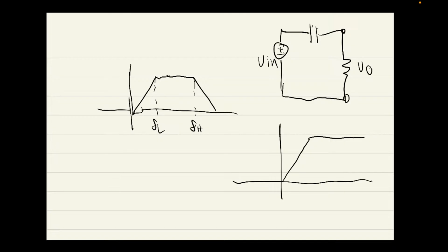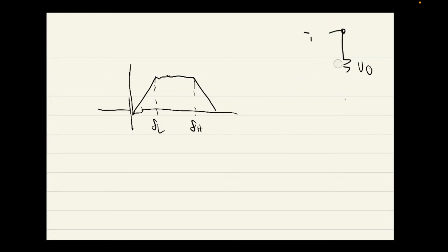There's a bit of intuition that you can build. But the main gist is that when you have a circuit that's got a lot of capacitors in it, you can't easily eyeball these things. You can't easily make a transfer function, V out on V in, as some complex-valued rational function in the S domain.